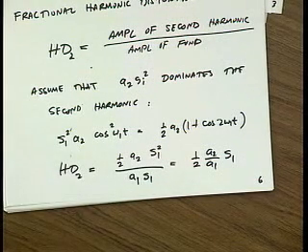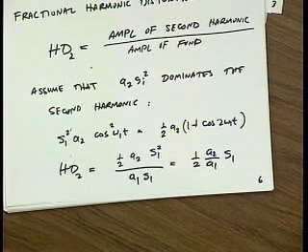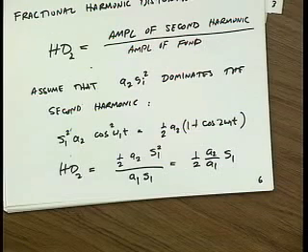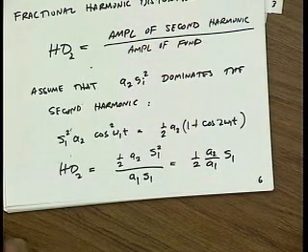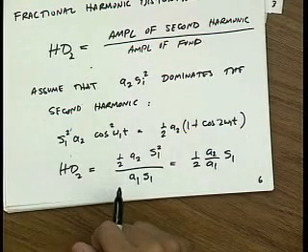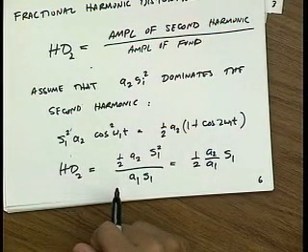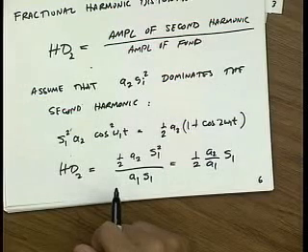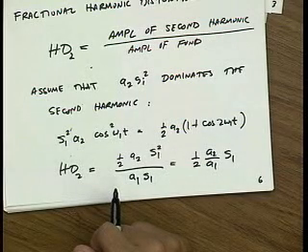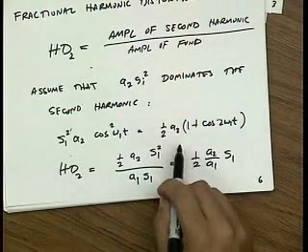Why should the second harmonic be of concern if it does not generate any in-band frequency component? The second harmonic is of concern because, first of all, it's generating distortion in someone else's band. Might not be your band, but someone else exists at second harmonic. Secondly, because it generates DC.